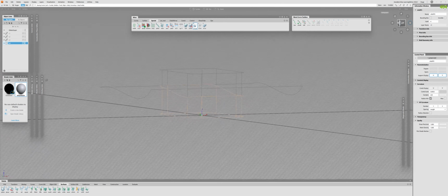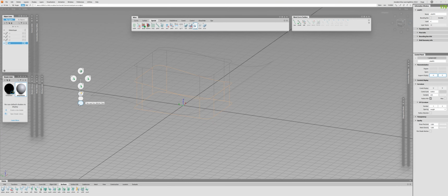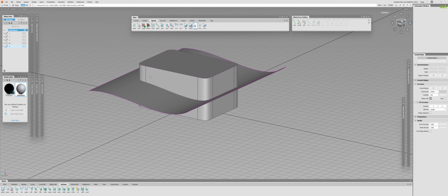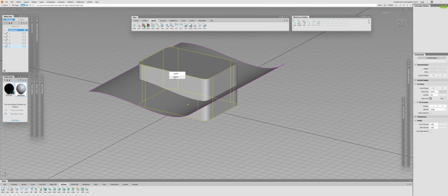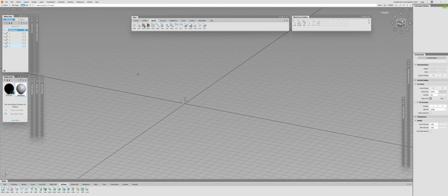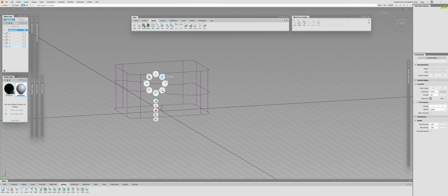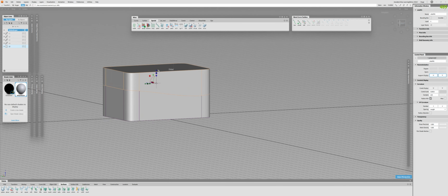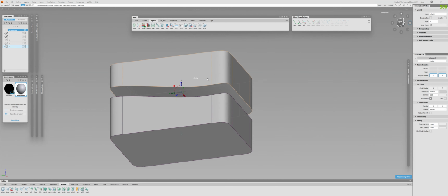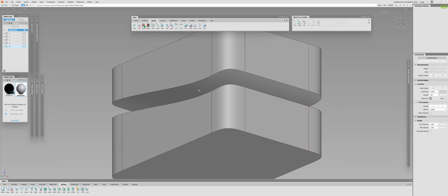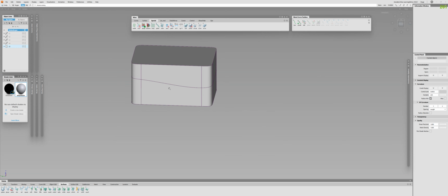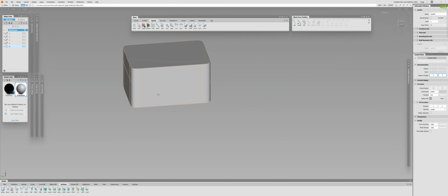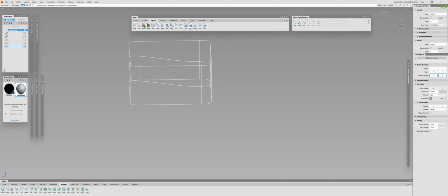So click and click. Right, so we have one object ready. Let me create a new layer and place it there. And the next operation will be intersect. Yeah, here we go. Let me pick it, just assign it and hide everything. So these are my two pieces. What's cool about that is now when I push it up, you will see that it actually has its own surface. So it has a cap, and this one has the cap as well. So basically Alias did everything for me, and now I can just select both of them, unstitch them, and proceed